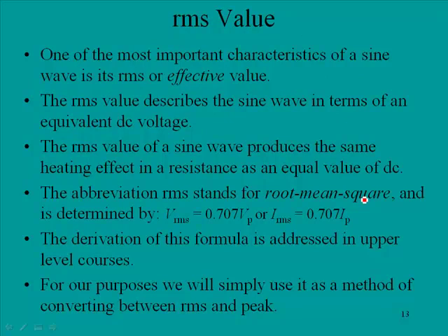Okay, RMS value. One of the most important characteristics of a sine wave is this RMS, or oftentimes it's referred to as its effective value. The RMS value describes the sine wave in terms of an equivalent DC voltage. The RMS value of a sine wave produces the same heating effect in a resistance as an equal value of DC. Okay?